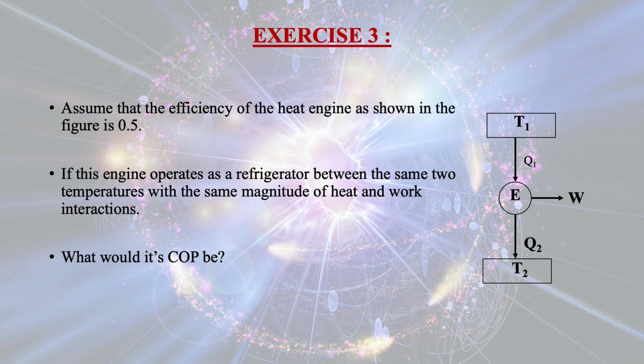Exercise 3. Assume that the efficiency of heat engine as shown in the figure is 0.5. If this engine operates as a refrigerator between the same two temperatures with the same magnitude of heat and work interactions, what would be its COP?